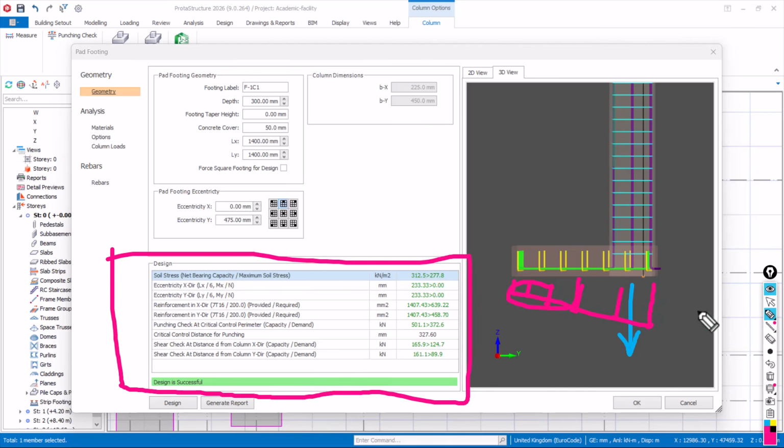When that happens, what occurs is that it will cause an overturning moment, like this. You will also have another one going like this, because it is trying to cause uplift. When this happens, what are you going to do? That is when you have to apply your engineering judgment to provide a counterweight, or to transfer the force on this column to a different footing.